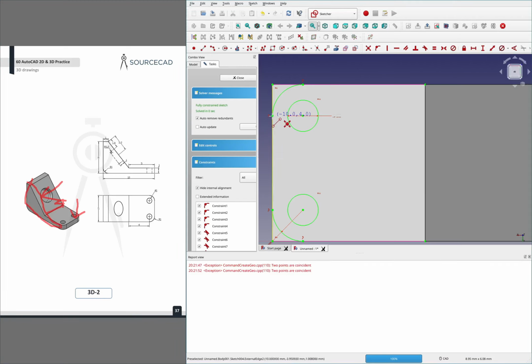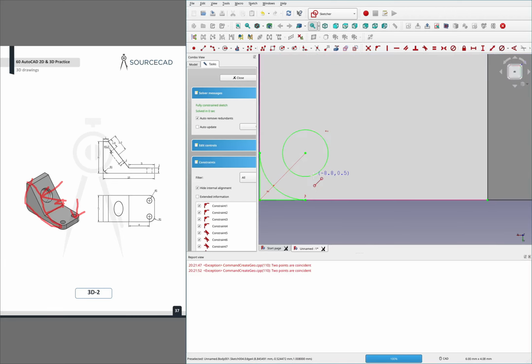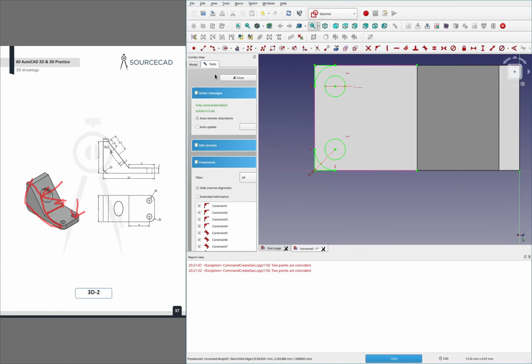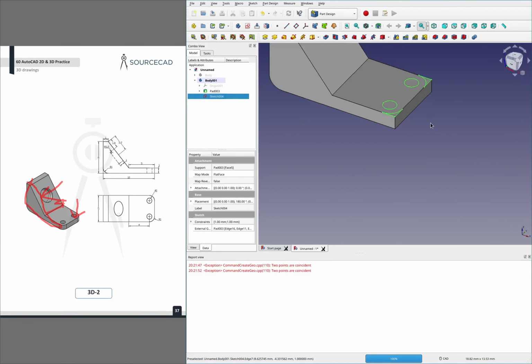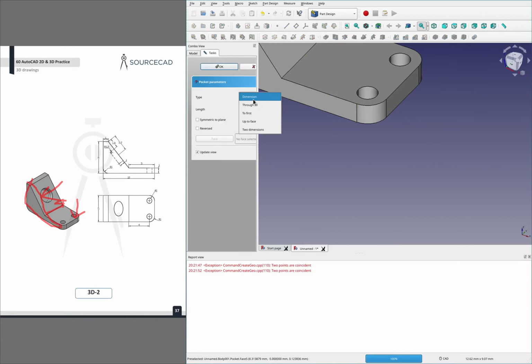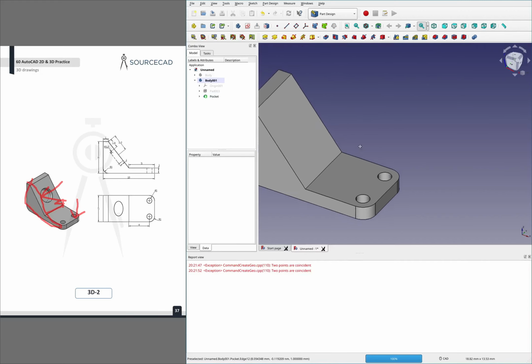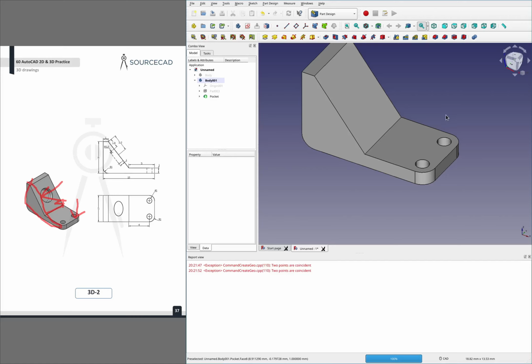And then lastly, I'm going to play connect the dots here, get the edges of my fillets together. If you didn't do this and you tried to extrude it, I expect that it would only grab the circles, or it might not extrude at all. So then we'll cut, dimension through all. Okay. And that is those.